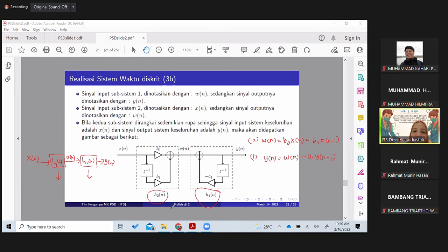As you could see, for this second direct form, for this kind of system, you will need two shift register memories, one for the input here and one for the feedback of the output here. And then you will need 3 multipliers and 2 adders.